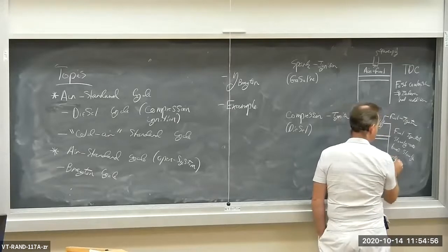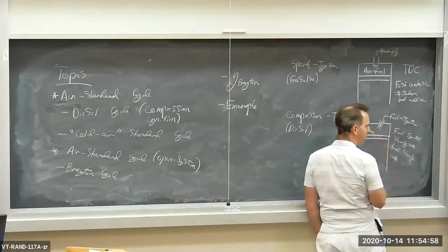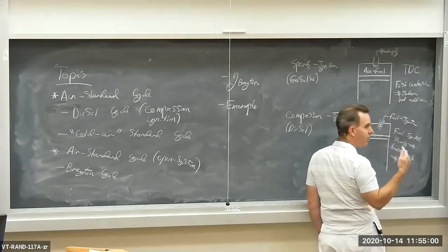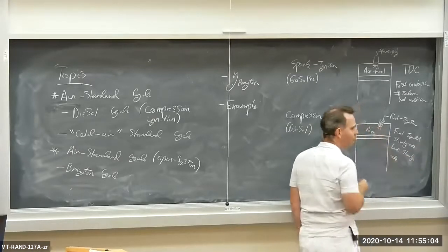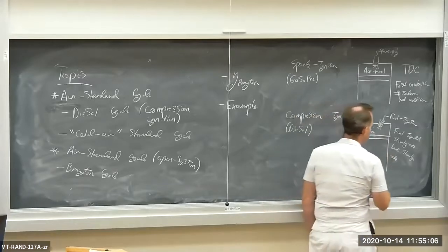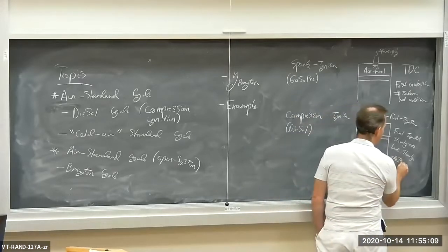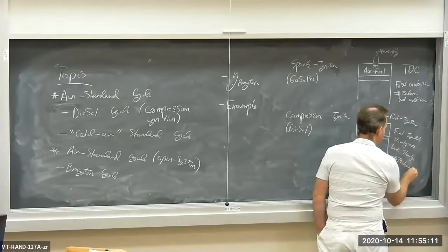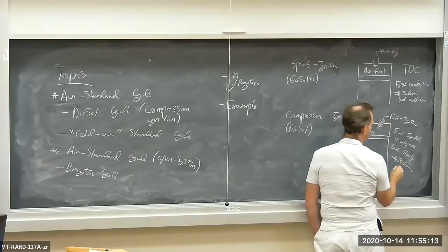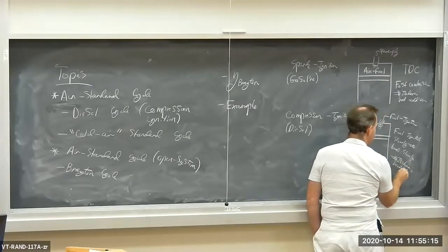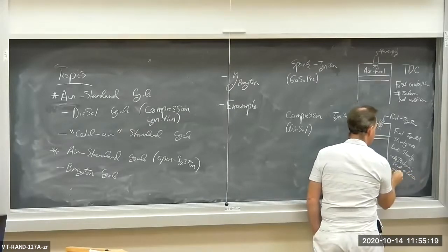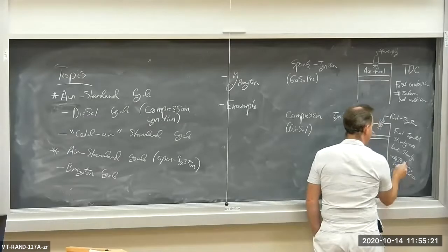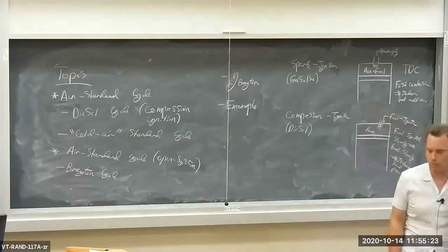The fuel burns slowly, so we assume that the heat addition process, i.e. the heat release during the combustion or burning of the injected fuel, is an isobaric heat addition process.